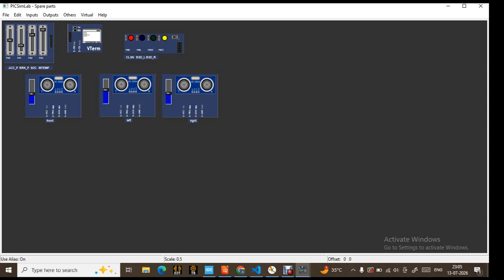Generally, green indicates normal operation, everything is safe. Blue indicates information or active status. It shows live sensor readings or active ADAS features, for example, ultrasonics or distances. Yellow represents a warning and advisory, the driver should be cautious. And red indicates a critical condition, immediate action is required.